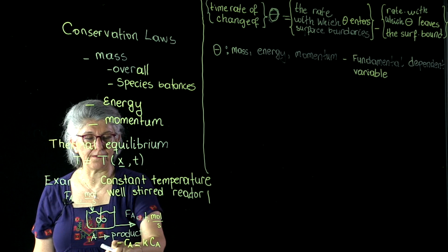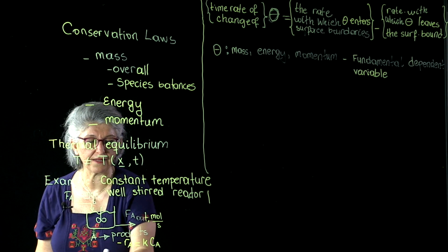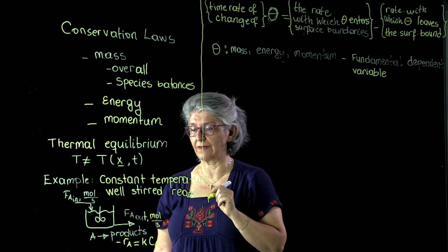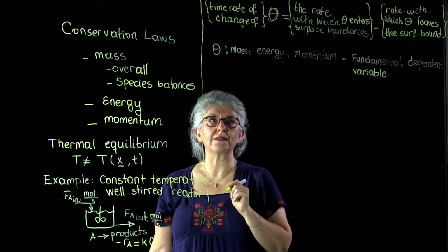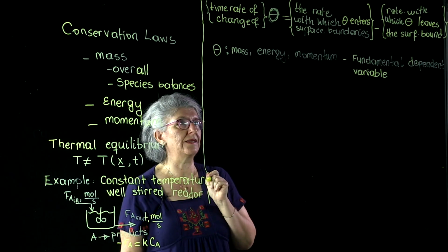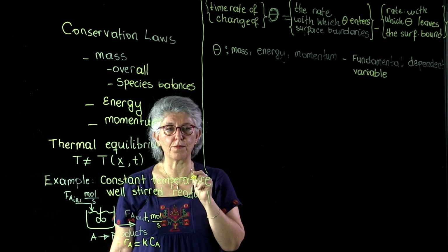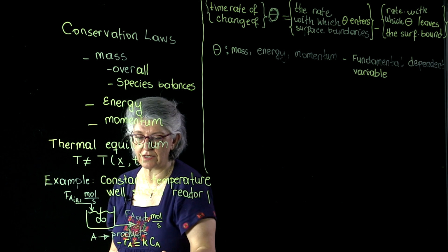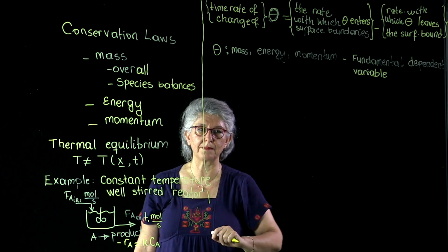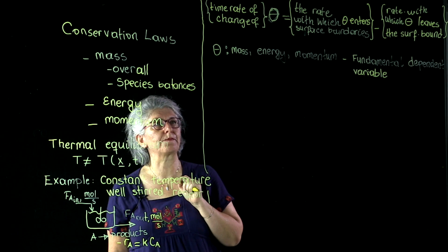Now we can write the conservation law for mass, but mass balances are very difficult to solve in terms of reaction kinetics expressions. It is very difficult to incorporate the rate expression into the overall mass balance. And we can relate mass to moles, and we can write mole balances, which are easier to handle mathematically, and we can incorporate this constitutive relationship of rate expression in the mole balances and solve this problem with more convenient mathematics.